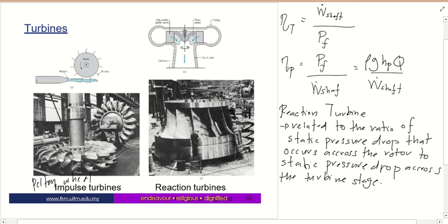Both the pressure drop across the bucket or blade, and the change in the relative speed of the fluid, which is the fluid speed relative to the moving bucket, across the bucket are negligible. As you can see, this is the bucket; for the turbine we call this a bucket, and we can also call it a blade. The space surrounding the rotor is not completely filled with fluid, so it is the impulse of the individual jets of fluid striking the buckets that generates the torque.